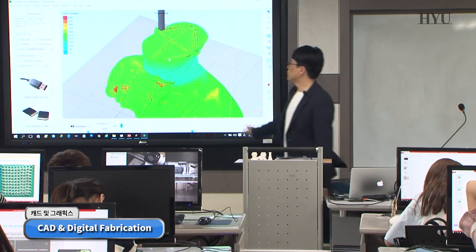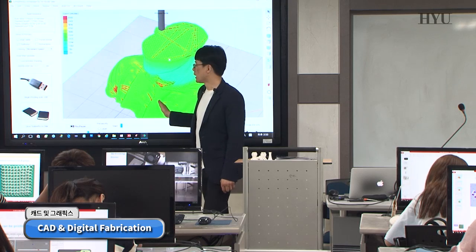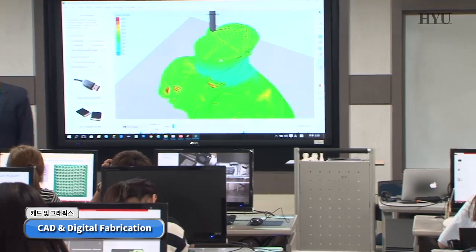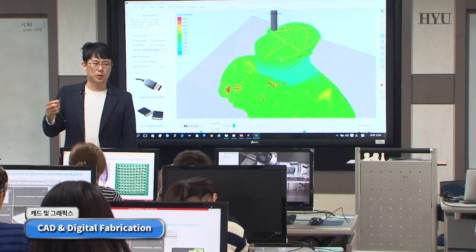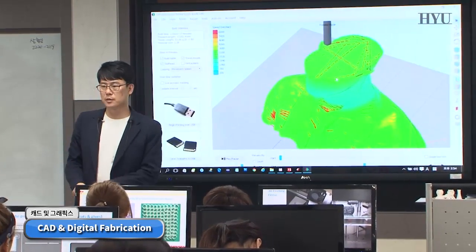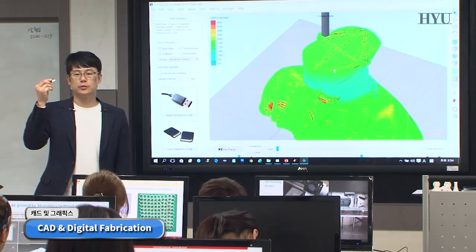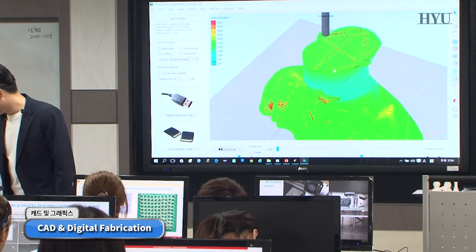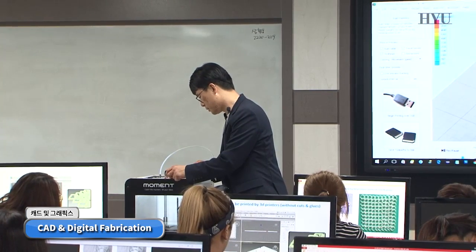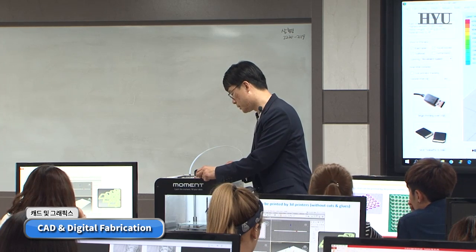So the file for defining this process is the so-called G-code file, and you need to save this one onto this SD card. Okay, so making your object, anything else, using SketchUp, 3D Max, and save this kind of G-code file onto the SD card, and then simply plug it in and click print, navigate to your file, okay, and let me print.